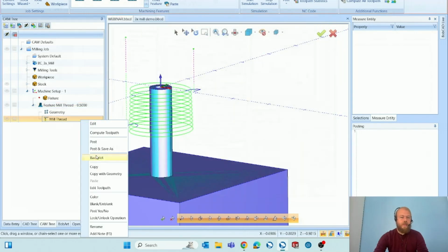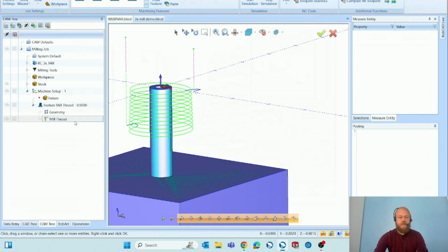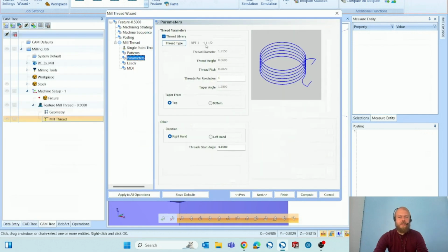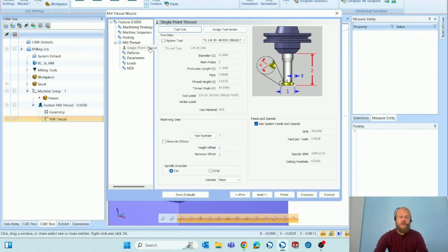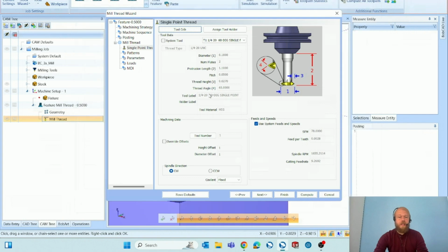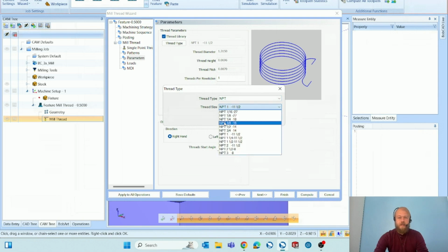But yeah, whatever type of tool you're using there, you can go in to the... oh, I guess you also have to go to the tool page and select that tool as well. So you have to select the tool in the tool page, and also under parameters, select the thread type under the thread type and thread size there.